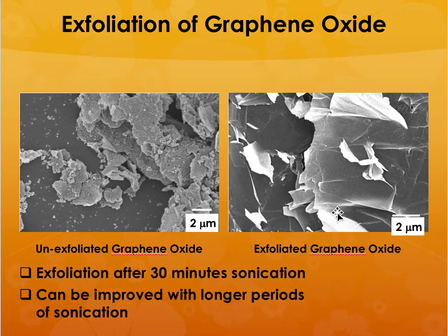And what we found is that by adding the graphene oxide or POSS to the polyvinyl pyrrolidone, we were able to exfoliate the graphene oxide, so it gave us extra surface area for the reaction between the graphene oxide and POSS molecules with the matrix resin system.